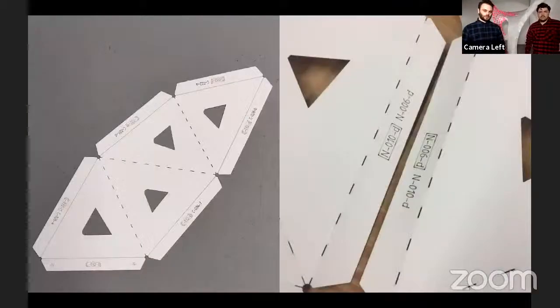And jumping into zooming in on these strips, each strip is comprised of multiple triangles, not always 4, maybe some are 3 or 5. And at the edges of each strip, as you can see on the right side of the screen, on the tabs, there's the assembly information. So breaking it down, in the boxed letters, you see N, 10, D. N refers to the subassembly that is comprised of numerous strips. 10 is the name of that strip, so each tab on that will have the number 10. And then D is the identifier for the tab. And you can see next to that, it says N6D, and that's the one that's across from it on the table there. So you can see that N10D pairs perfectly with N6D.